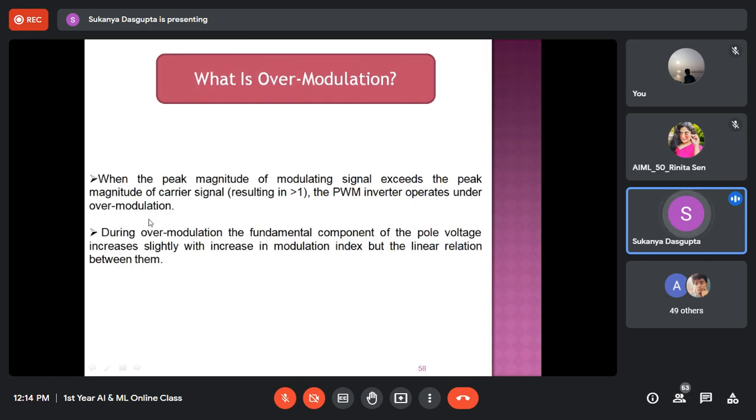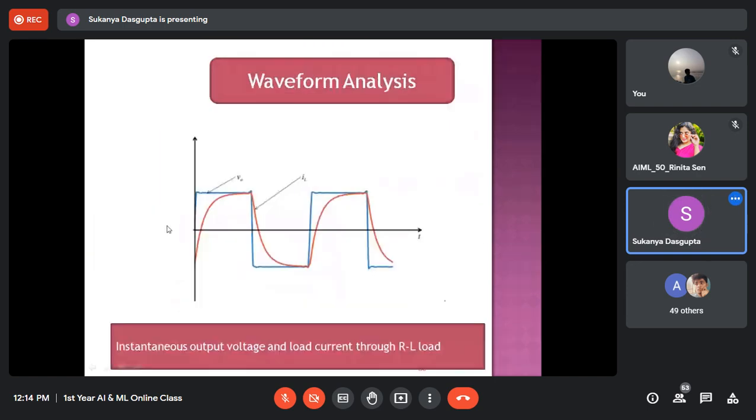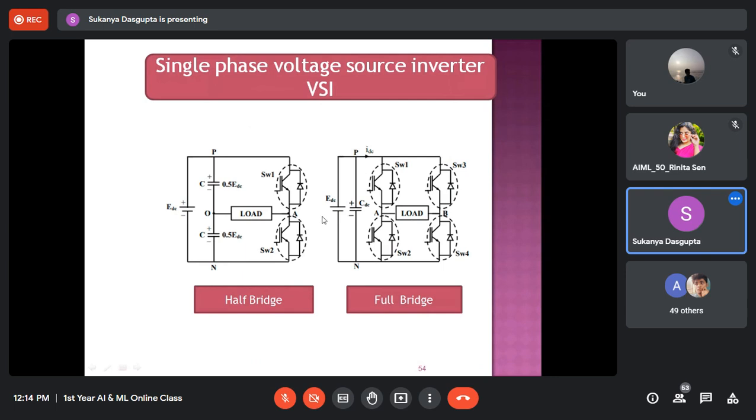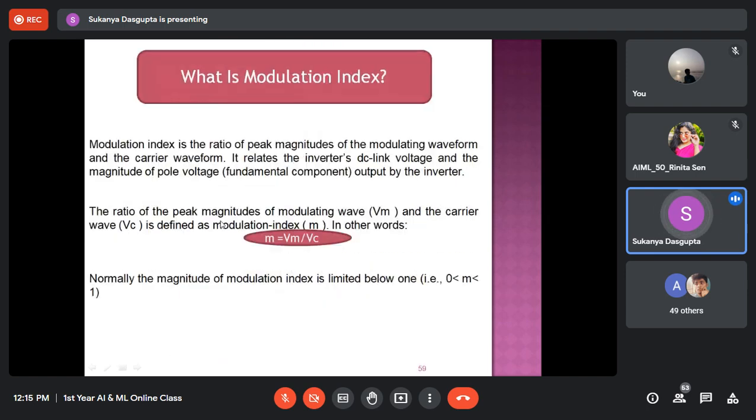So that's why we need to have this type of neutral point or common point across the input so that we can measure the pole voltage, because pole voltage means the voltage difference between the center point between the two switches in one link with respect to this common point, neutral point. That is called the pole voltage, right?